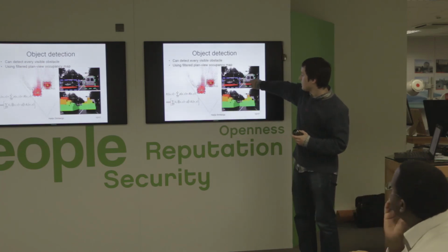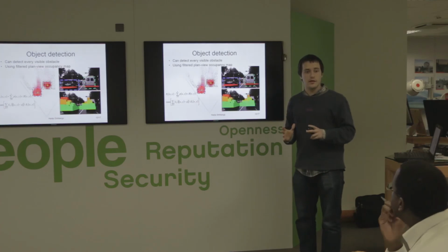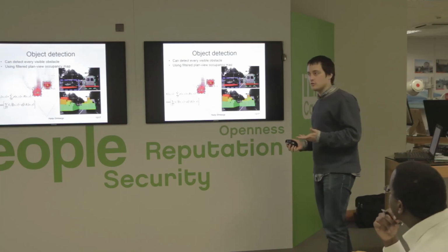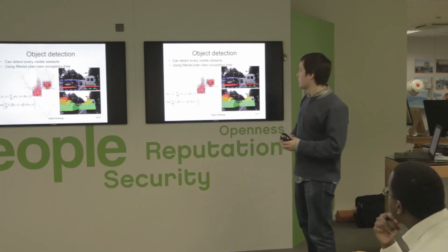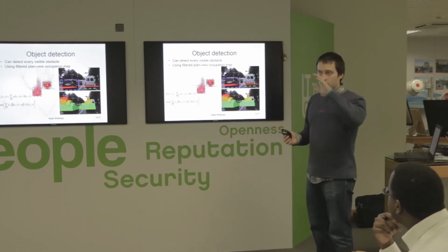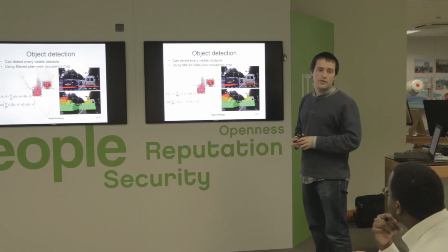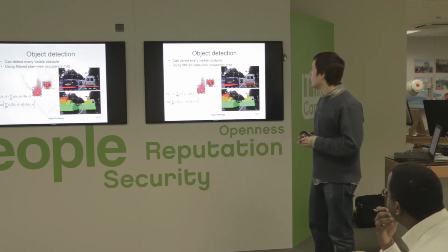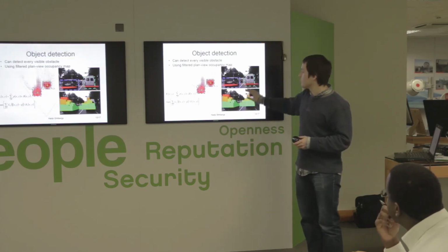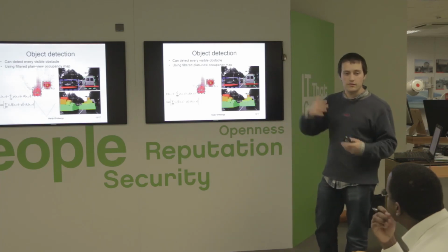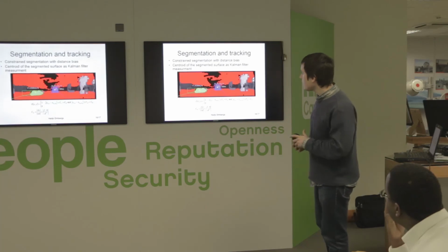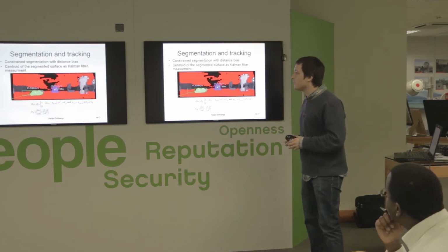But you can see that it actually detects objects that are partially occluded, which I usually can't detect with regular image analysis. Usually cars, for example, are detected using symmetry, using shadow on the ground, and so on. There are many algorithms to do it from one image. In this case, though, most algorithms would fail. But in a 3D point cloud, you still see it because it's a physical object, a physical thing in the world. Then there's the segmentation and tracking itself.